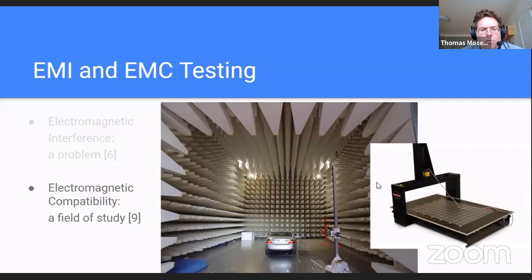The EMC scanner is a device roughly the size of a 3D printer, which is able to measure the EMI in a high range of frequencies. The radiation analysis is done with a near-field probe attached to an XYZ robot, which reads and later on renders a 3D graphic visualization of the electromagnetic field around the tested object. The scanner is usually meant for precise readings in small components like circuit boards.